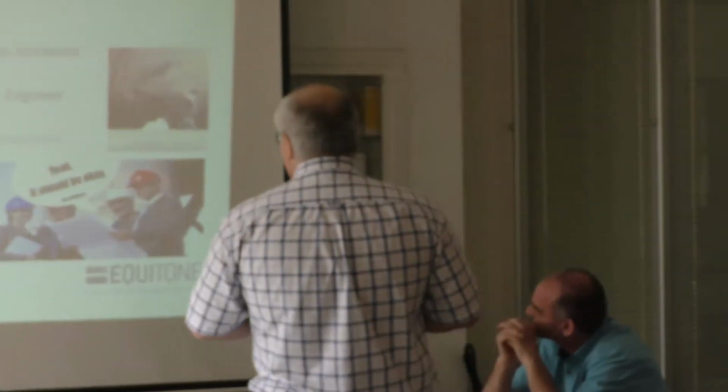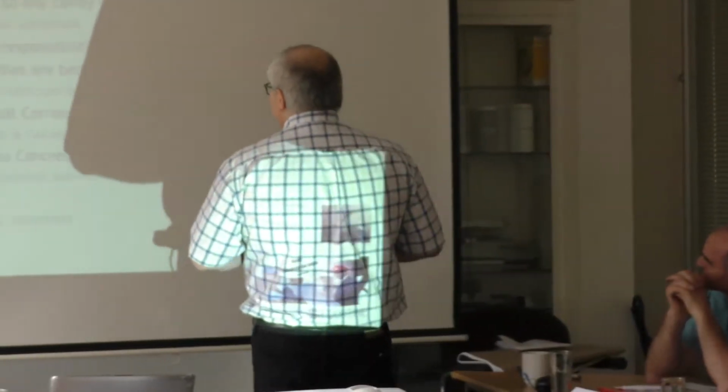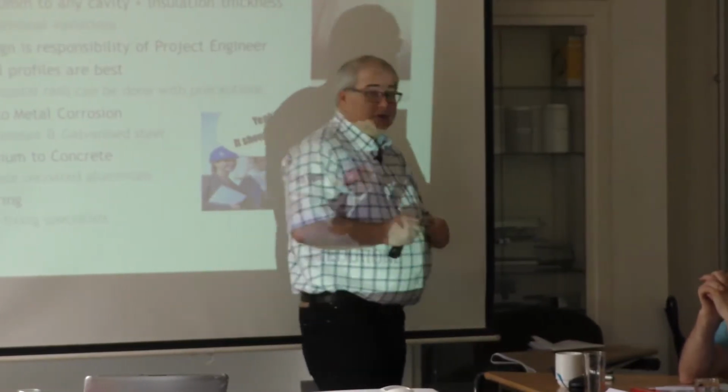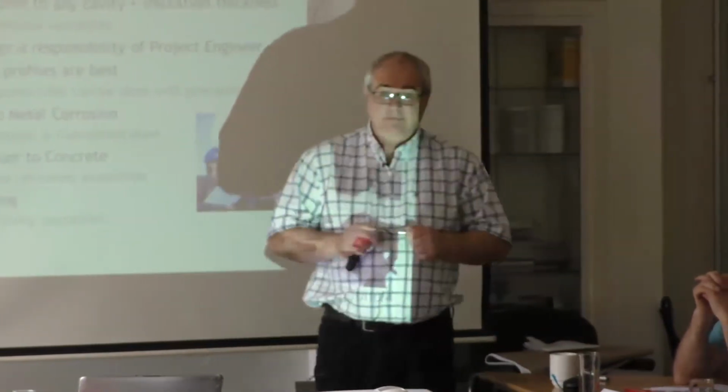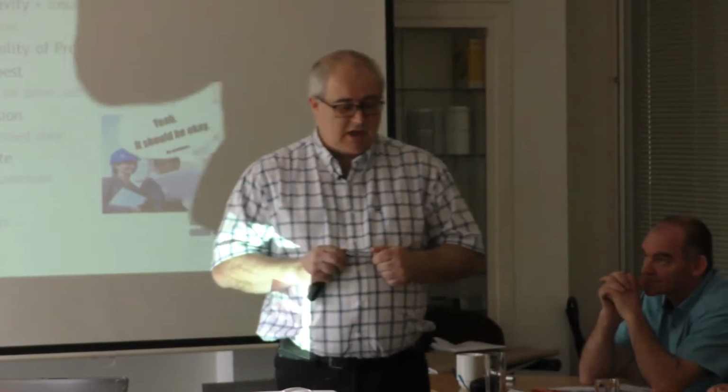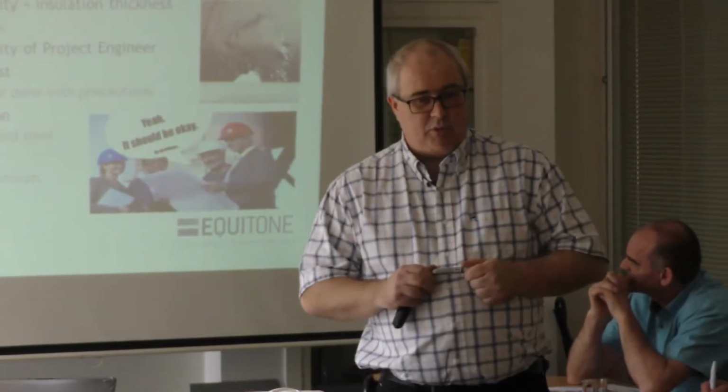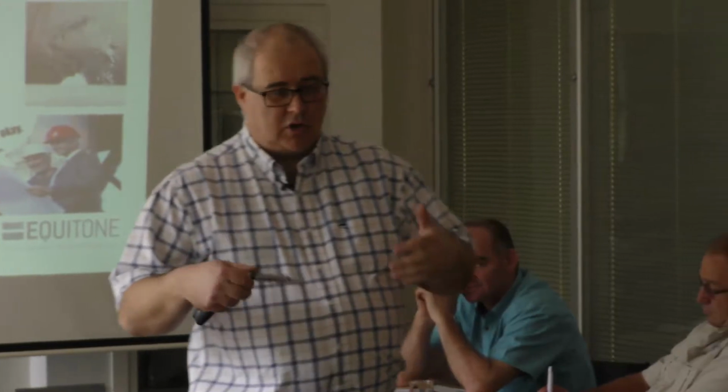Somebody asked me the question that always gets asked at this point. What size of cavity do we have to use? Normally we would say you can go down to a minimum of 20, but then again, depending on the building and how tall the facade is, that will have to increase. It could end up being 100.